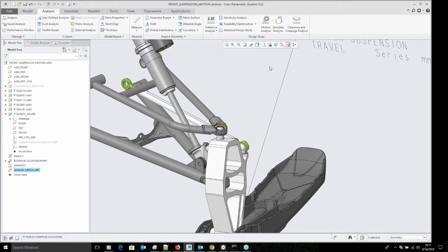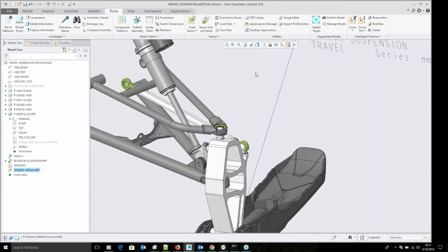So now that we have that set, the next step in the process would be to publish those sensors. Back here on my tools, I would have a connection back to the ThingWorx platform. So we would connect up to the server, or I would publish that information, basically saying I want this sensor to share its information from the snowmobile out in the field and transmit live data back to the ThingWorx platform, and then have that results information be available to me as a designer. So that's going to look like this.